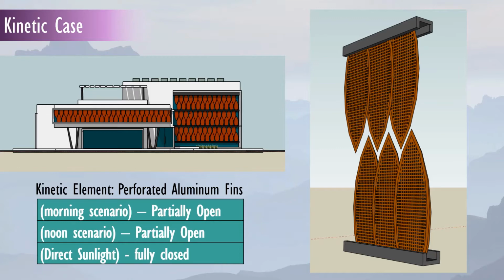As for the kinetic case, perforated aluminum fins were used as shading elements. Strategies are: south and west facades to be open in the morning scenario, east and west facades to be open in the noon scenario, and all elevations closed in extremely hot summer days.